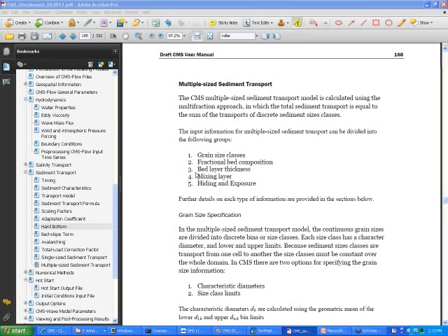Most of the time, it's hydrodynamics and due to very bad bathymetry or boundary conditions. Boundary conditions will produce instabilities if they're not well defined, if they're in the wrong place, if you have noise in your water surface elevation boundary, things like that.